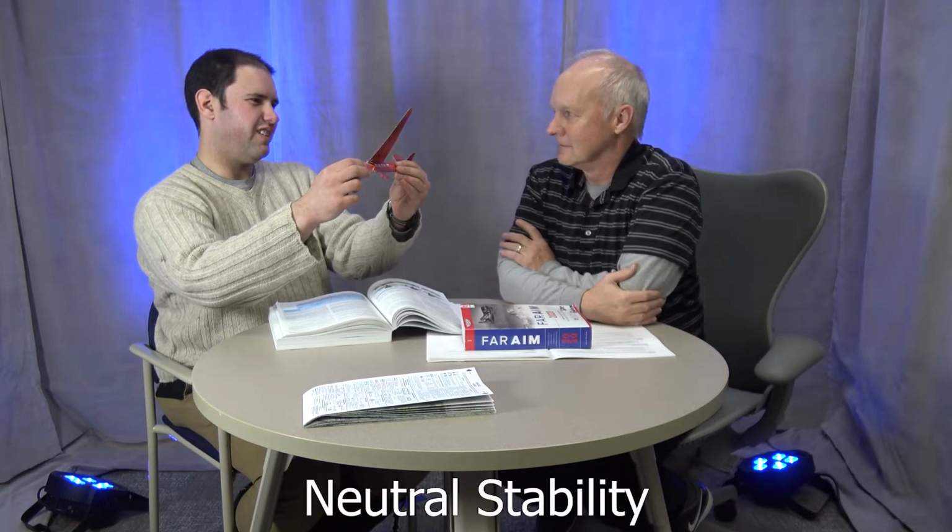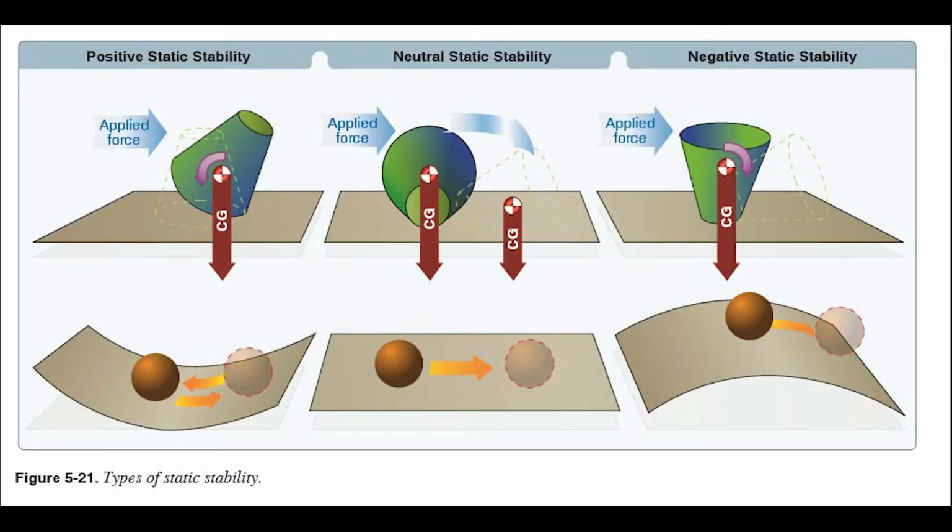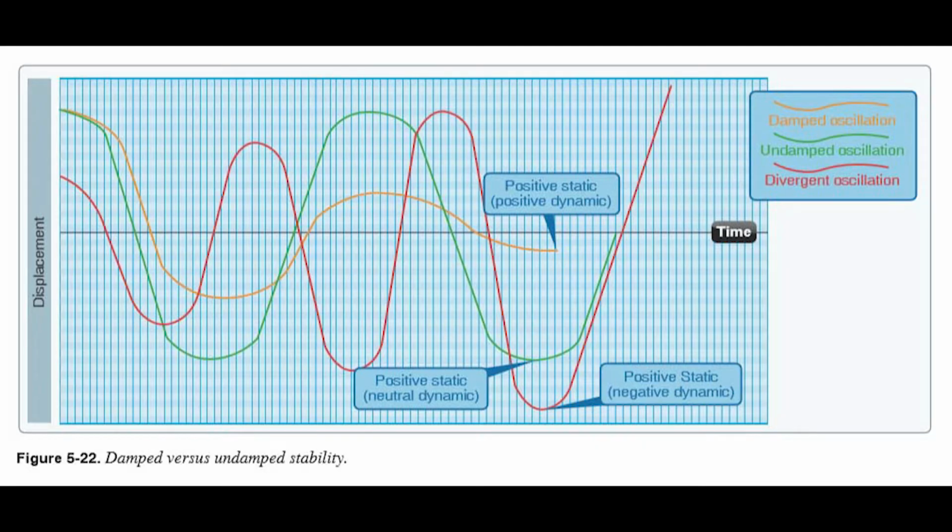Well, something else interesting is when we talk about positive or negative stability. Positive stability is it wants to come back. Negative stability is it goes further over. If it just stays where you put it, that's neutral stability. That one certainly had it. And they've got a little graph here on figures 5-21 and 5-22 showing static stability, positive, neutral, or negative, and then dynamic stability, positive, neutral, or negative, showing how that develops over time.